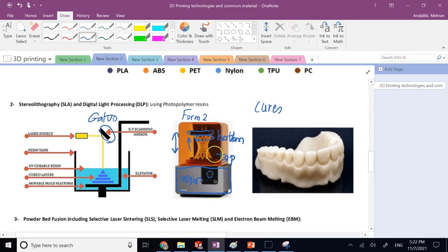So when you print with a resin printer, you want to have personal protective equipment, or PPE, specifically gloves and goggles, okay? And most of the time overalls, or you might call it coveralls. You don't want them to touch your skin or get into your mouth or nose. They are not safe. They are environmentally hazardous material.